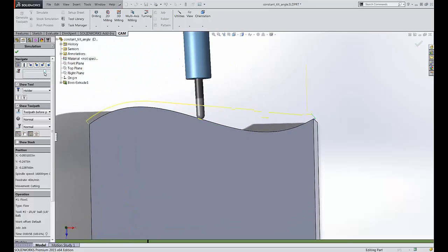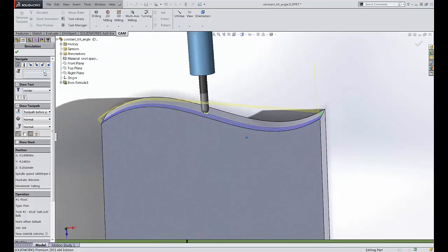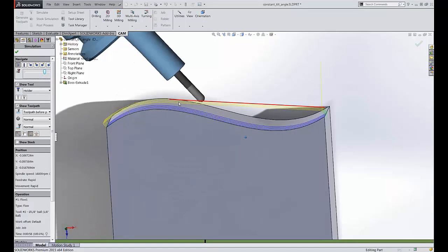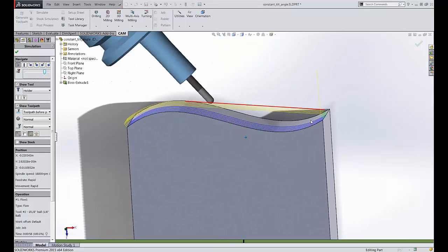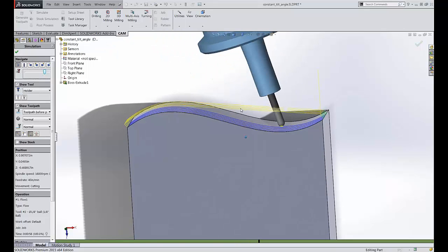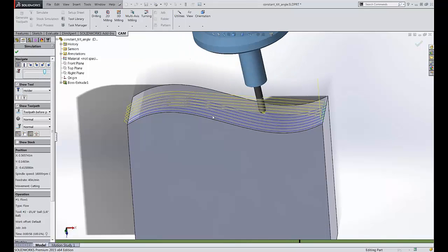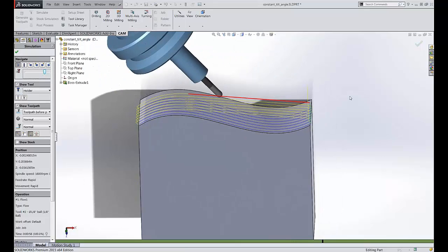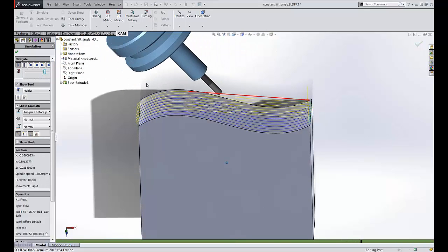And this, I think, is a great example of HSMWorks toolpaths just doing a great job. That stay-down linking right there is really pretty fancy. In this case, the vector in and out is pretty similar, but it's purely because of where I ended the surface. It's oftentimes neat to get ones where the vector changes, and you'll see that it smooths the tilt out over the entire move, which is pretty tough to do.